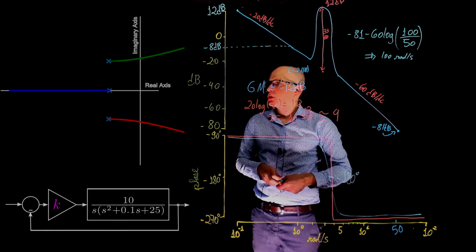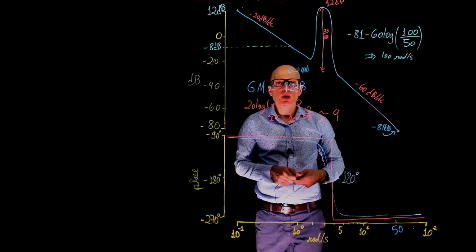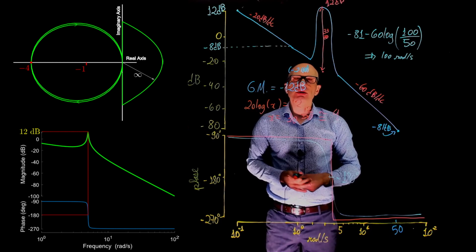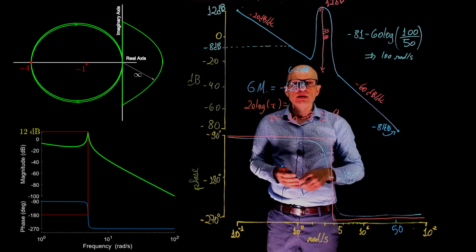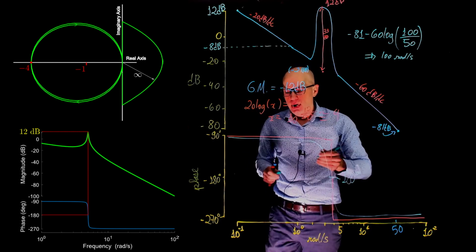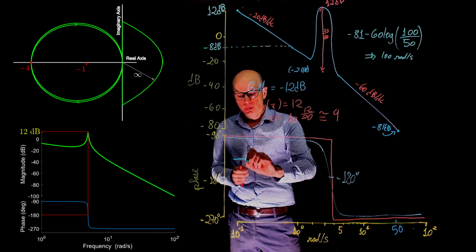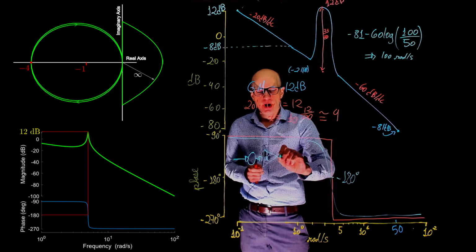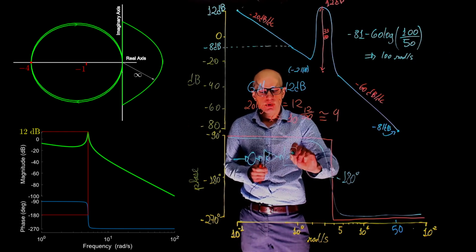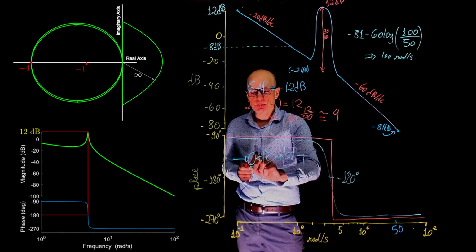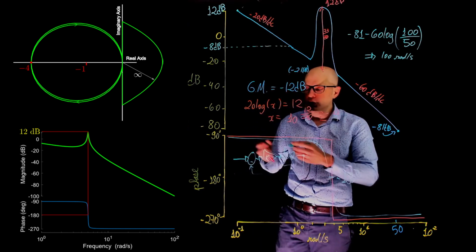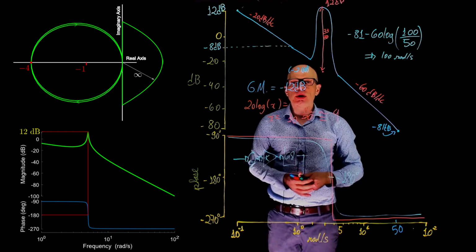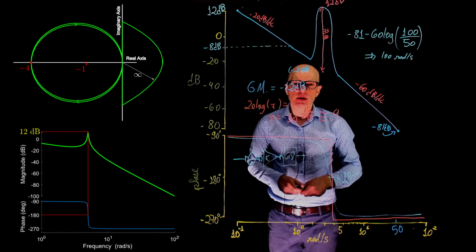So, the question now could also be, what makes the system stable? Let's put the Nyquist plot and the Bode plot together and analyze this question. What makes the system closed loop stable? Now let's reconsider the example we had before. So here is again k, we have the function g of s, and we are treating the system this way. The root locus that I showed you earlier had k equals 1. This Bode plot, this Nyquist plot also has k equals 1.